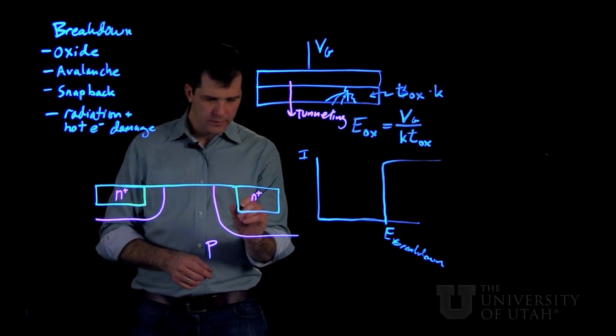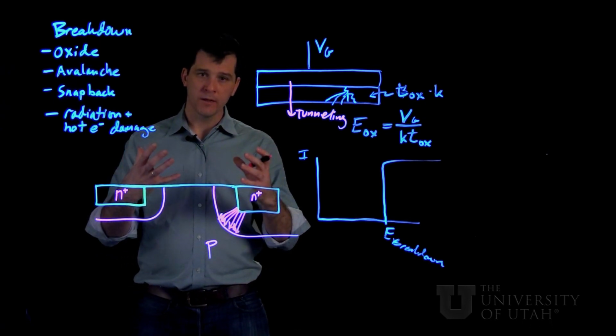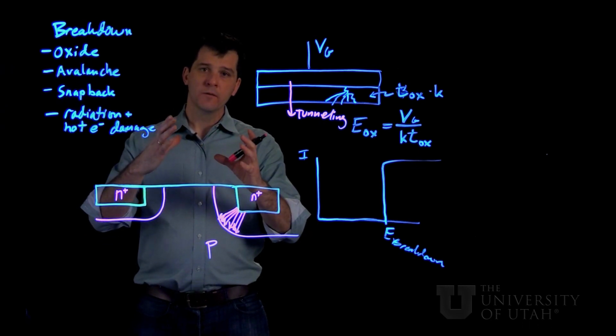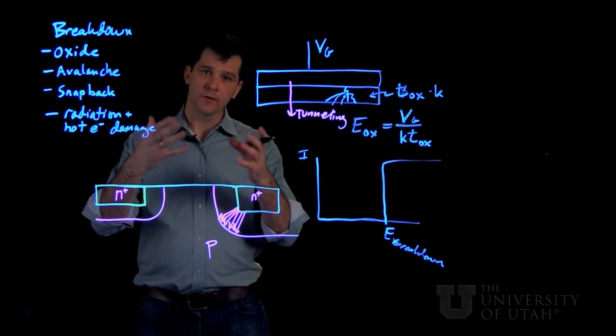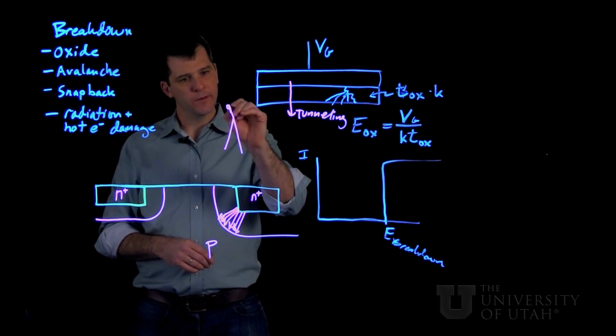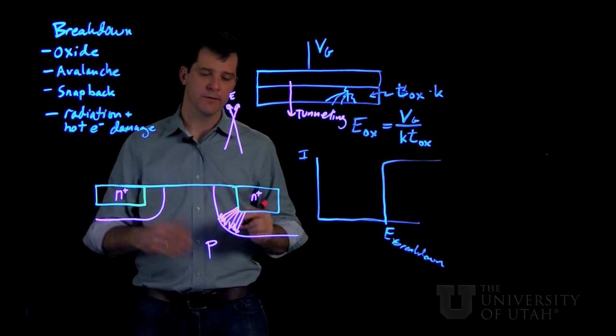So especially at these corners, the E-field will tend to build up. Remember that the E-field around any object will be inversely related to the radius of curvature locally. So a sharp point creates a very intense E-field and a multiplication factor on the average E-field.